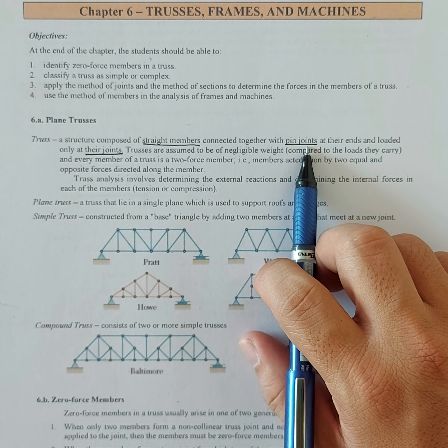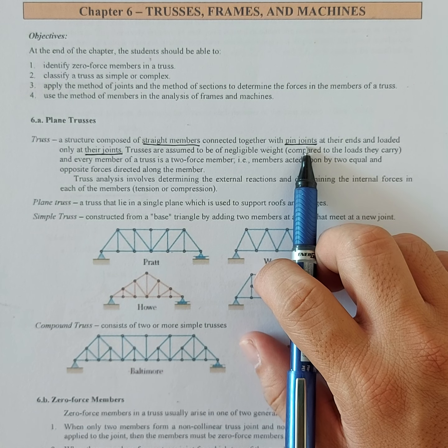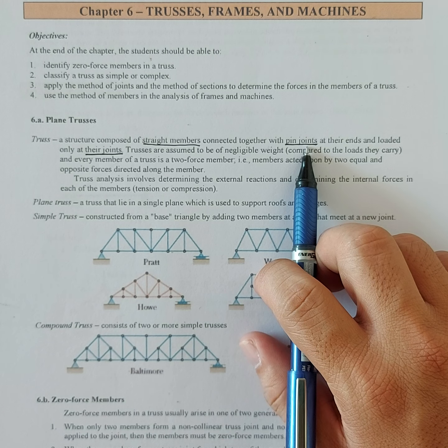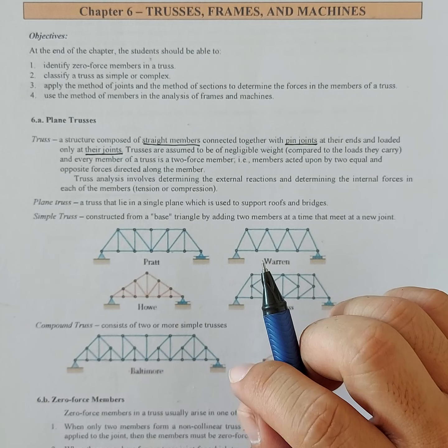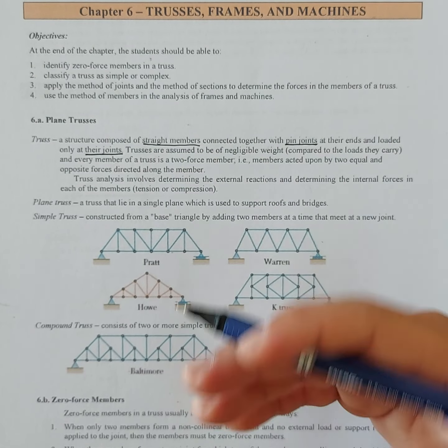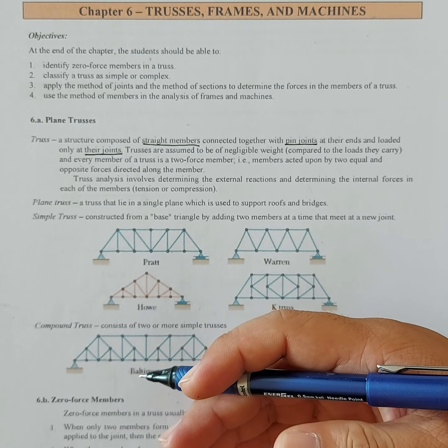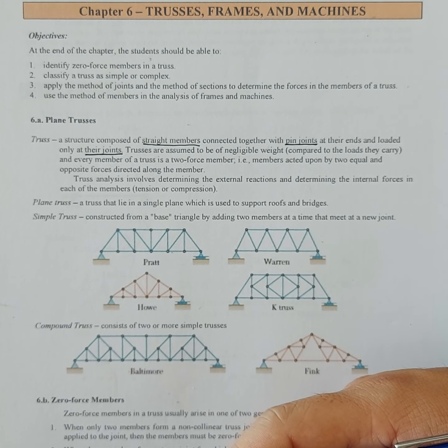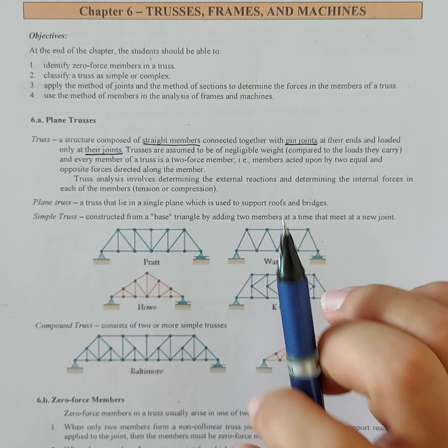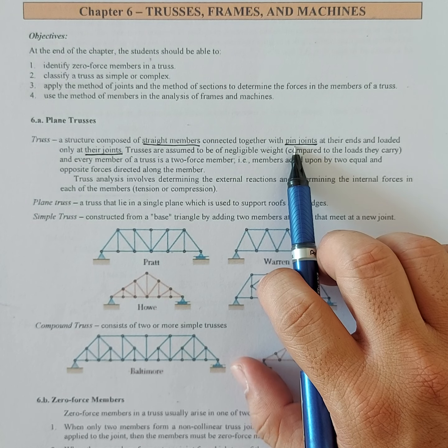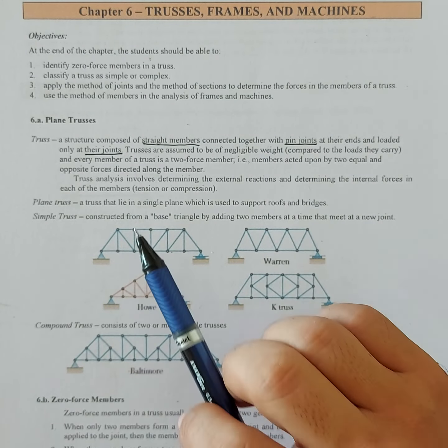In bridges, or other structures, sometimes the connections used are combined. They can be welded, bolted, or riveted. So they can be combined: bolted and then welded, or riveted and then welded. So these are the assumptions that we're going to make: that the joints are pin connected and the loads are applied at the joints.